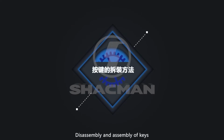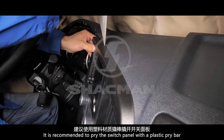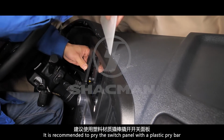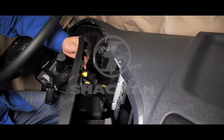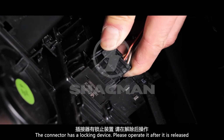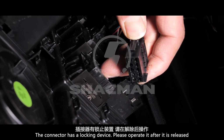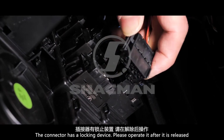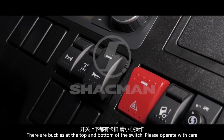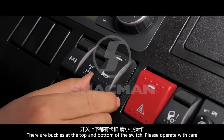Disassembly and assembly of keys. It is recommended to pry the switch panel with a plastic pry bar. Bayonet position. The connector has a locking device. Please operate it after it is released. There are buckles at the top and bottom of the switch. Please operate with care.